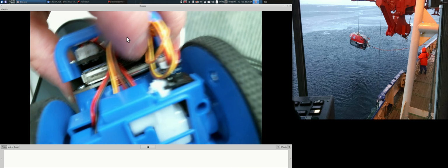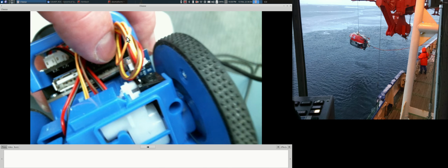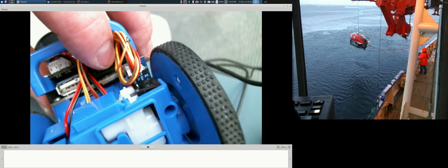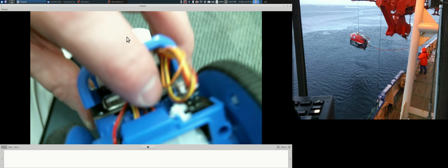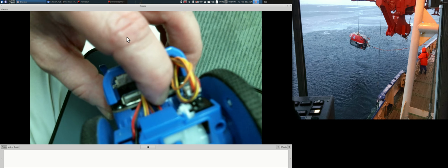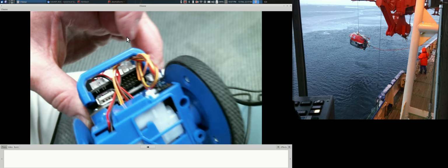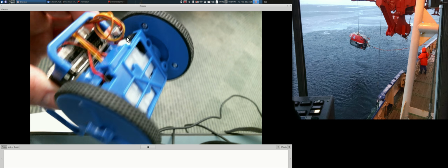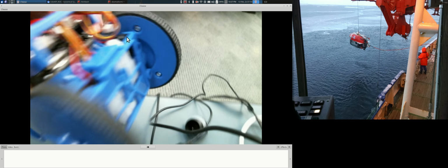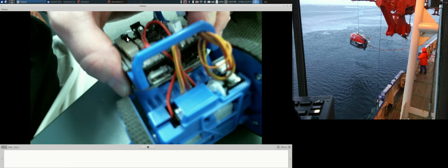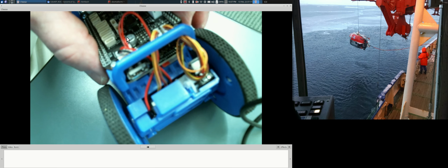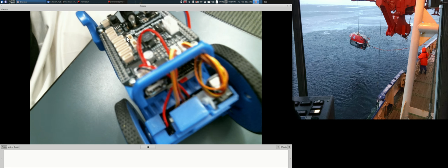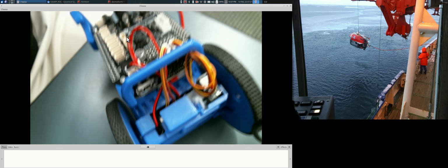And so I use a pair of tweezers just to reach in there and grab the card and pull it gently out. And then when I want to put it back in, I use a pair of tweezers to actually place it in the slot and get it oriented, and then I push it down with my fingers. I've got big, clumsy fingers, so your fingers may be small and able to maneuver in there just fine. But that's where it is. And on this one also, the gold-plated contacts face away from the board.